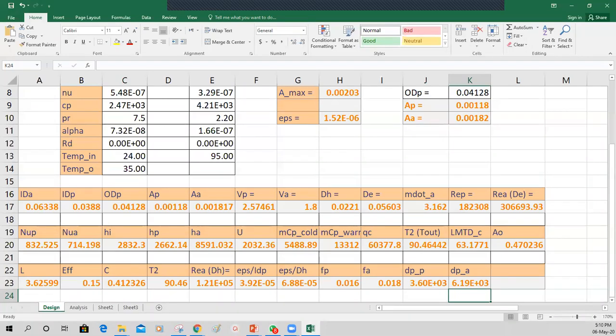Doctor, if it is out of constraints, like the pressure drop is high, do we change the annulus diameter? Very good. First of all, which pressure is out of the limit, pipe side or annulus side? Annulus side. If it is the annulus side, then one option is that you choose a larger annulus, one or two steps bigger.